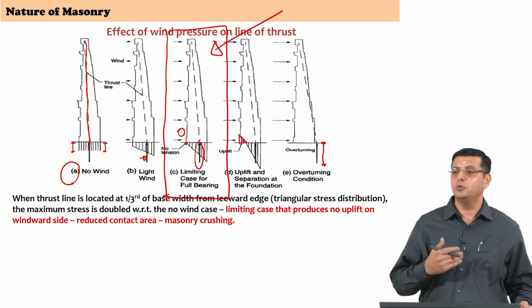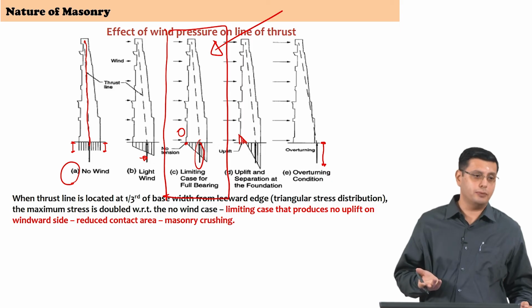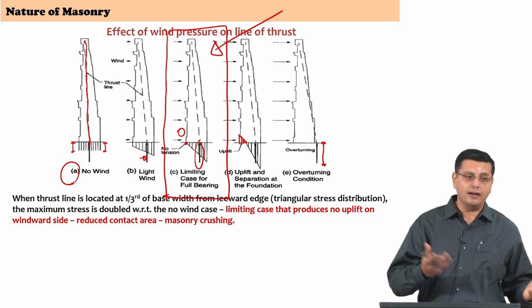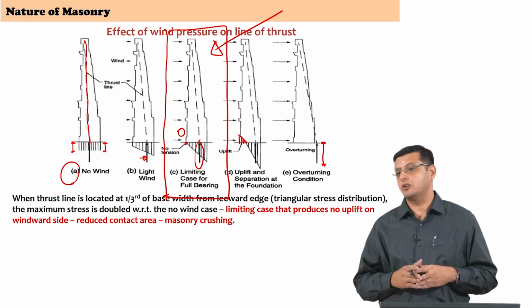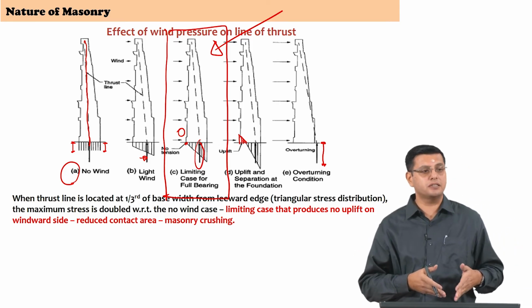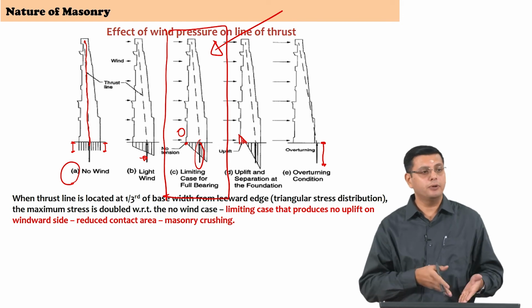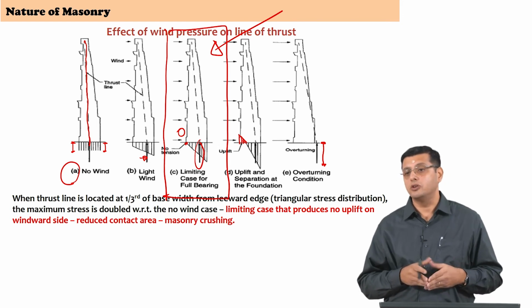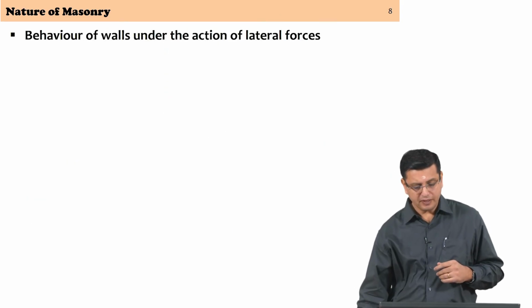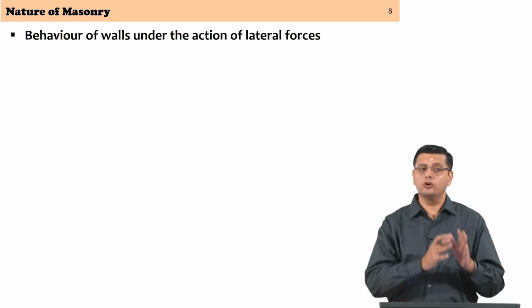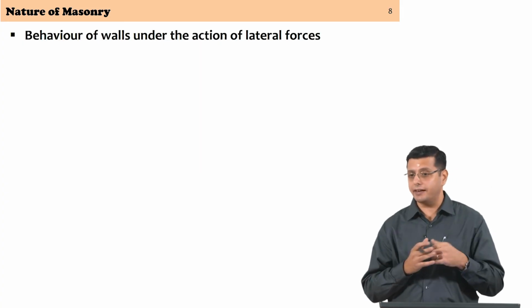Today, you and I are able to put reinforcement into masonry or have other elements that can give tensile resistance. So, we start reducing the cross sections. Here, if you reduce the cross section, it will simply overturn because of zero tensile strength available in the masonry. Okay. Having said that, here we looked at the stability under gravity and lateral forces.